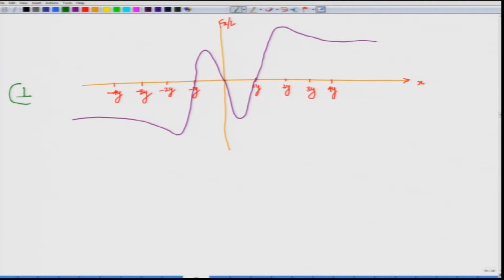So, this is the dislocation which is creating a stress field, and this is the dislocation onto which we are trying to calculate the force. So, it is onto this dislocation we are calculating f x by L, and when we say x equal to y, we mean with respect to this dislocation. So, this is the x, this is the y.